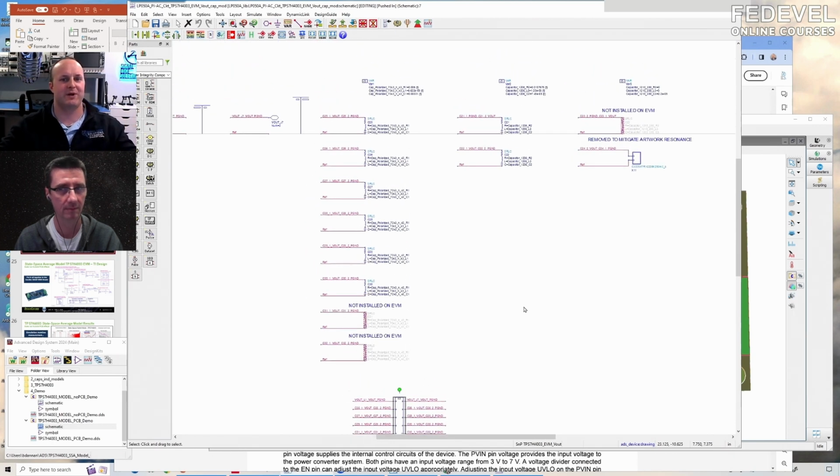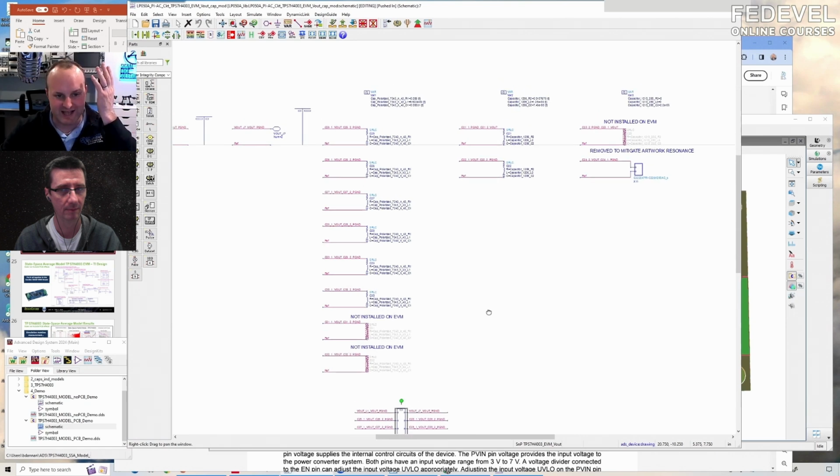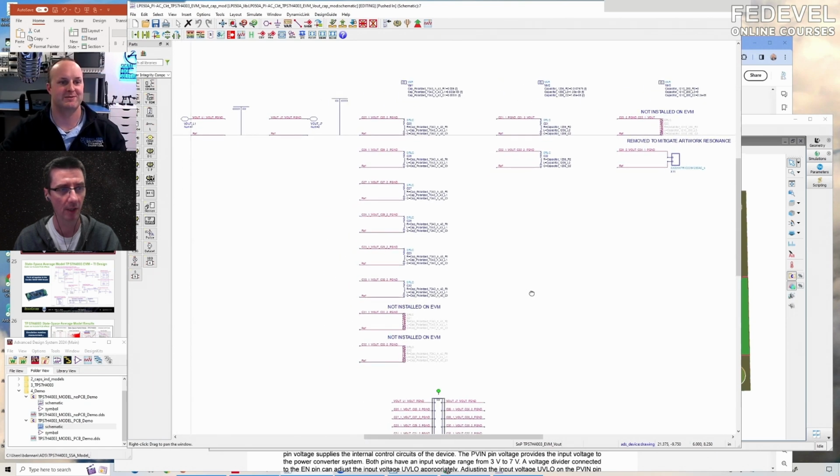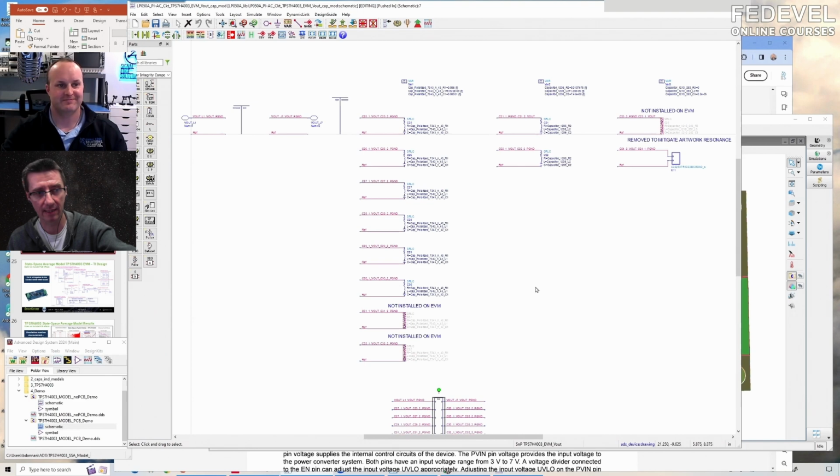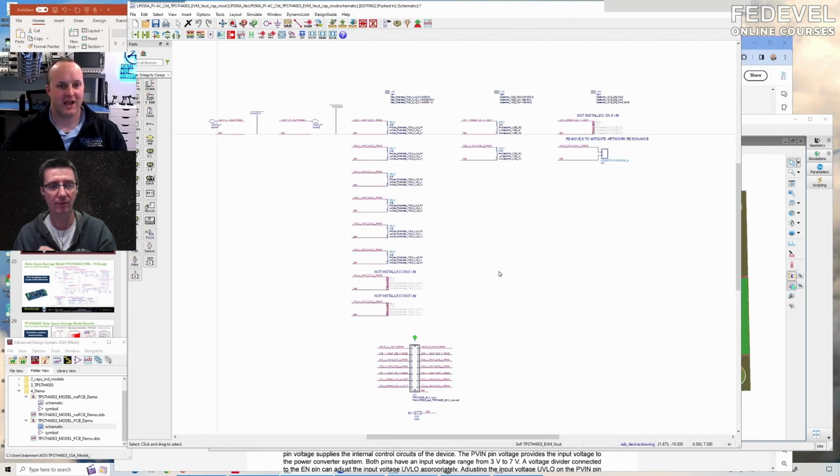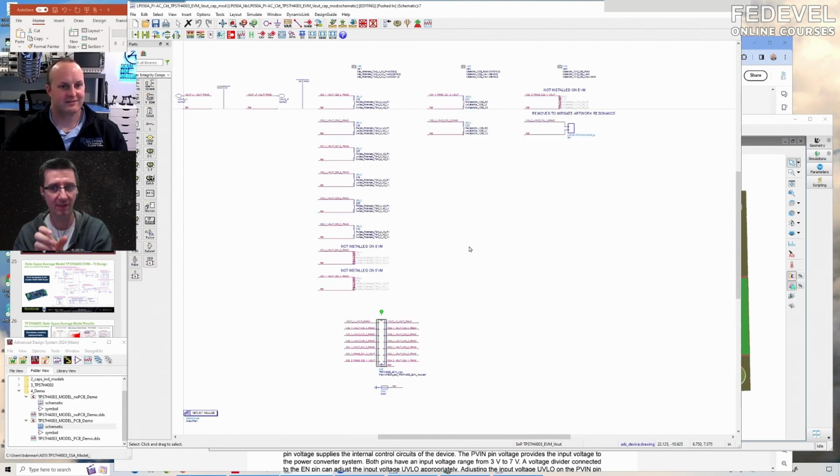Remember, this is an 18 amp supply. What do you do if it's 100 amp or 1,000 or 500 or 2,000? This is where the PCB effects have to be included. That's why the PCB model has so many outputs, because they correspond to the position of specific capacitors.